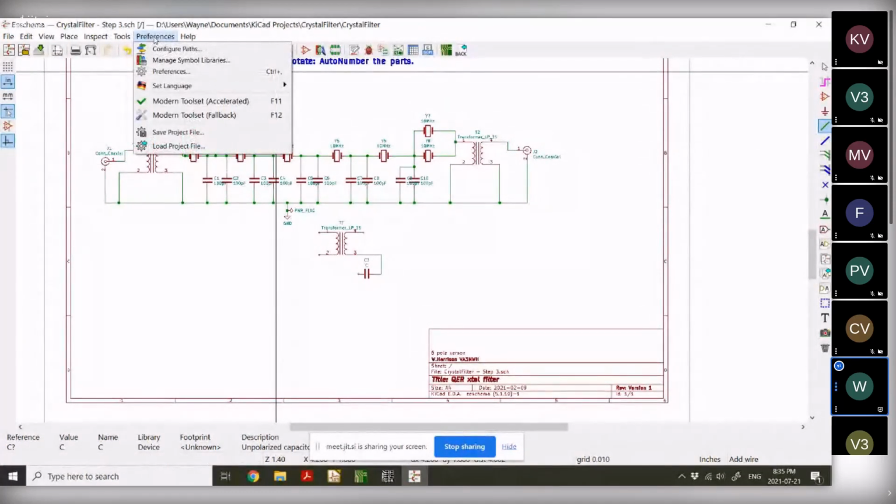What you do is you go to a vendor that supplies libraries. If you're finding the entire library at once, you're going to find it on GitHub. So DigiKey has its library on GitHub. I do not know if it's a complete library because I can see things on their catalog that I don't seem to be able to find in footprints. But it's big. And what you do is you go to Preferences, Manage Symbol Libraries if you're in this particular thing.